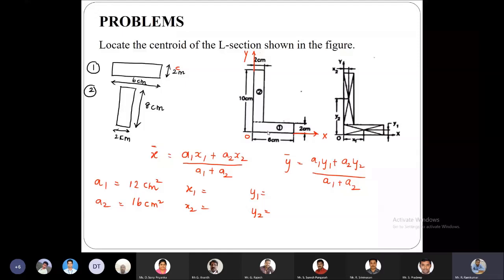So now let us replace all these W1 values with rho g V terms and W as rho V g term. You can see that the W1, W2 values are in the numerator, and the value of W is in the denominator. So when we are using that, the value of rho and the value of g will get cancelled, that is, if the composite solids are made up of the same material.